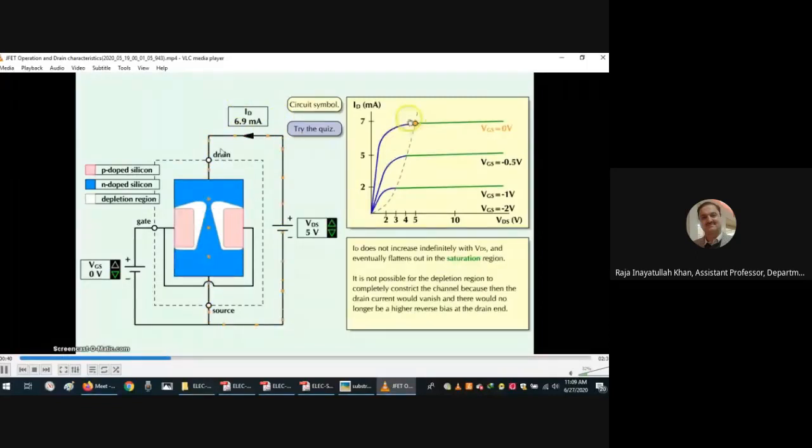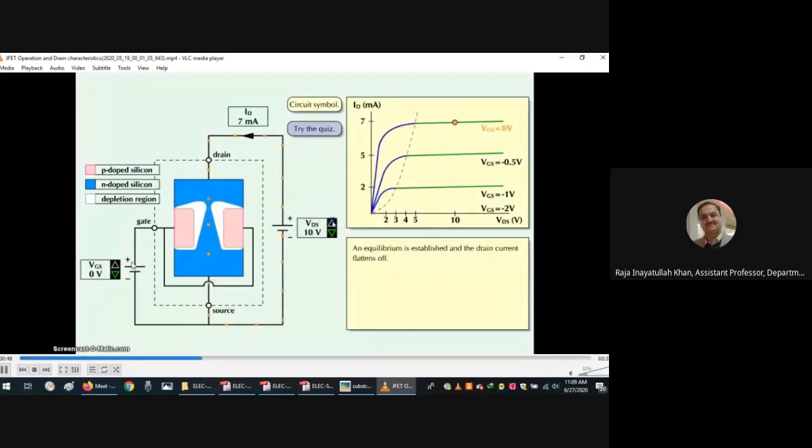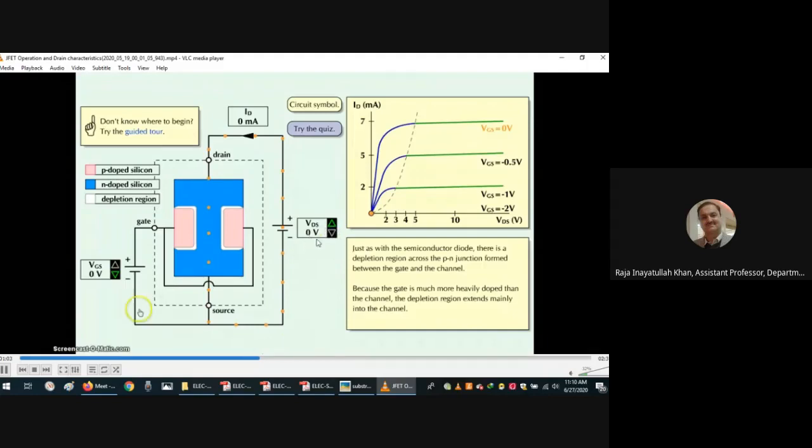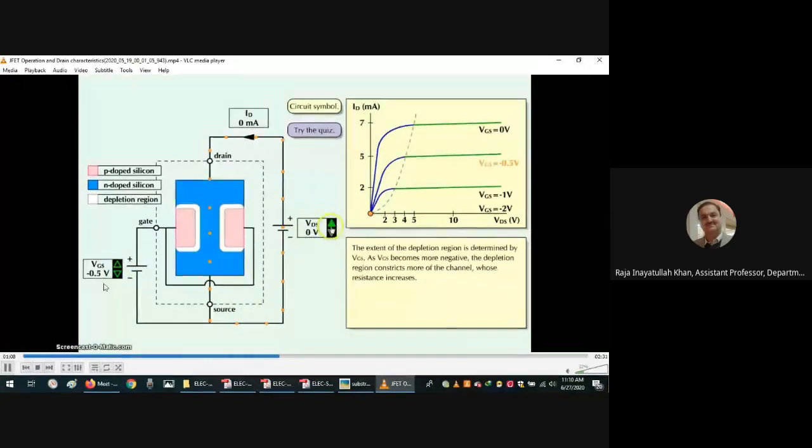There's a bit because the positive voltage is applied here, and still the gate is grounded from here. You can see, because of this, there is still a channel, a pretty big channel, where the free electrons are flowing. As it keeps on increasing, you can see here for 10 volt, the voltage is maximum. Now 0 volt is made VDS and a negative voltage of 0.5 is applied.